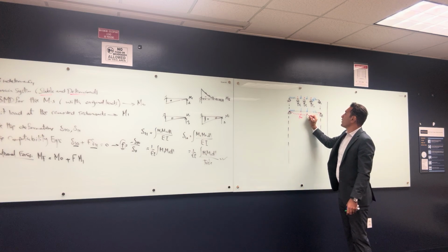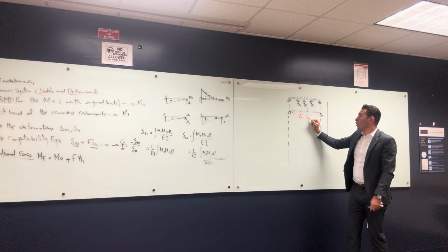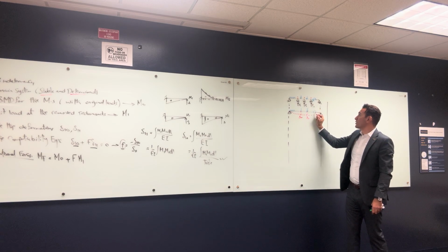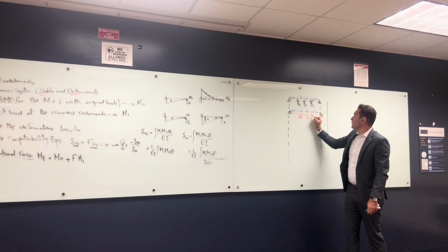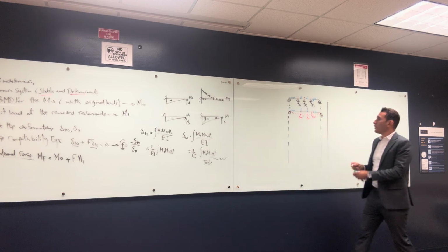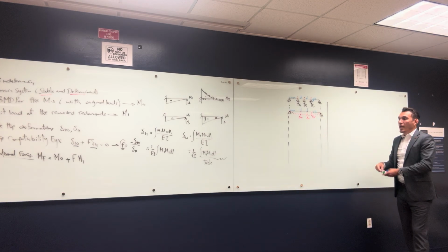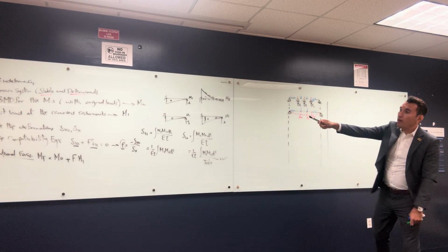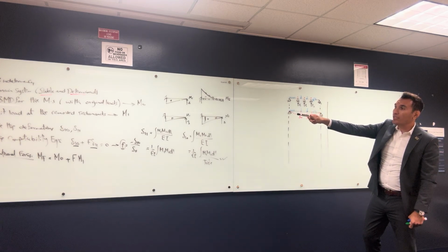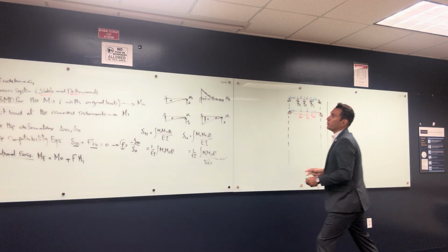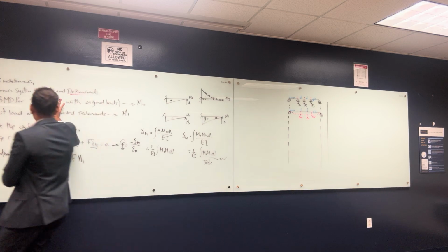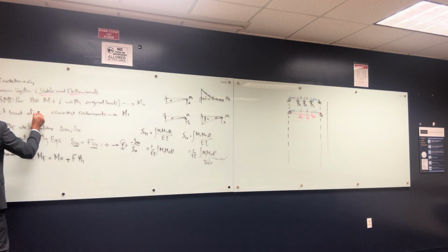So you guys tell me, how can I name this point? Delta what? 2O. Delta 2O at point 2 from the original loads. How about 3O? Okay, so these are all the deltas. And next, let's see. Put a unit load at each removed redundant.